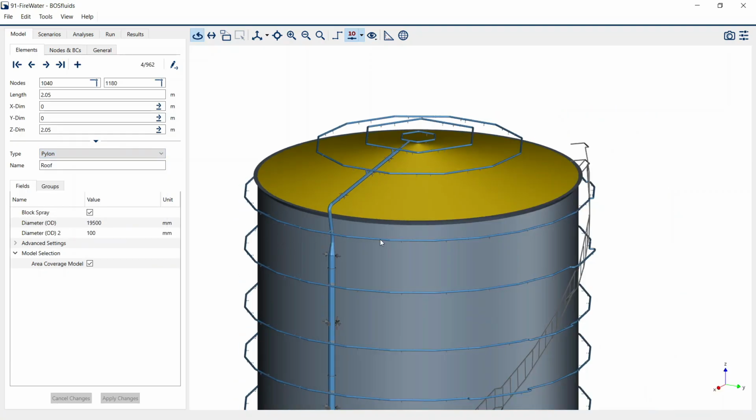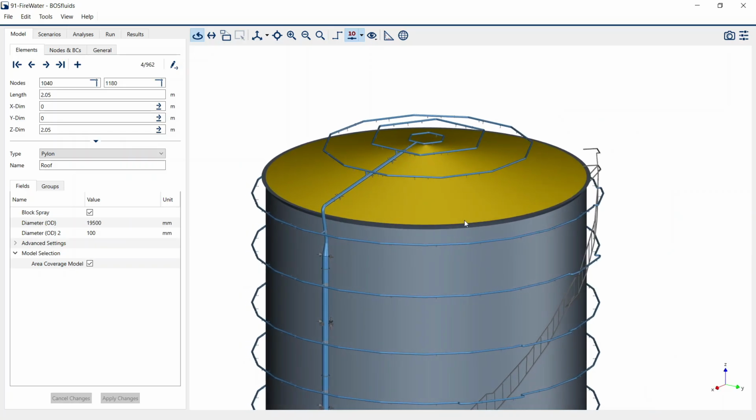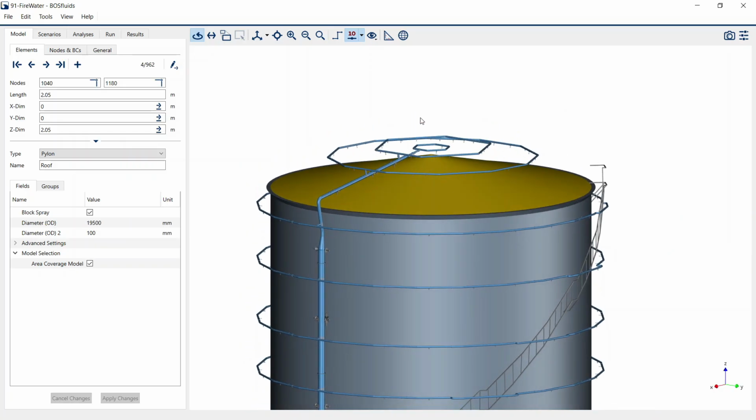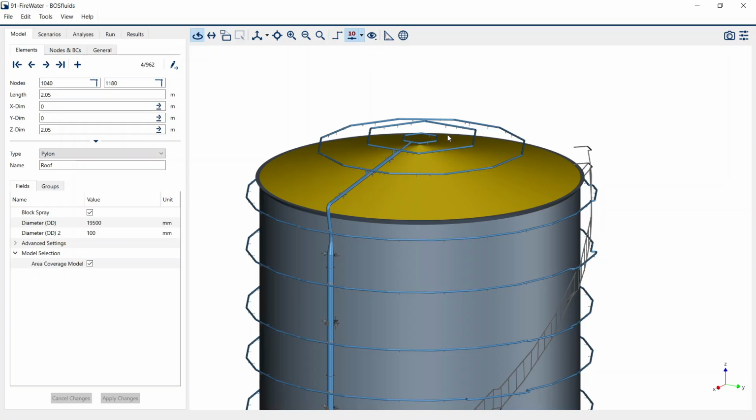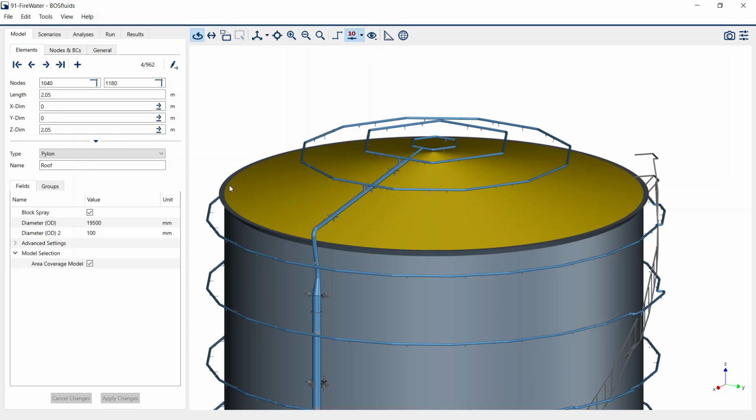And with that, you're very flexible in creating all kinds of surfaces where your firewater coverage is being analyzed. So, for instance, also if you have different kinds of pipes or features, you can use these surfaces because they also block spray that's, for example, being sprayed if there's something in between the surface you want to wet and the sprinkler.